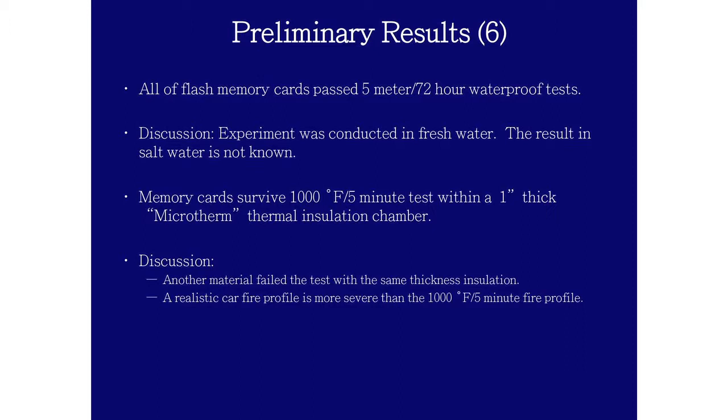And the memory cards can survive this fire profile using a microtherm material. It's a thermal insulation material used to build the black box in airplanes. And the other material we tested failed.